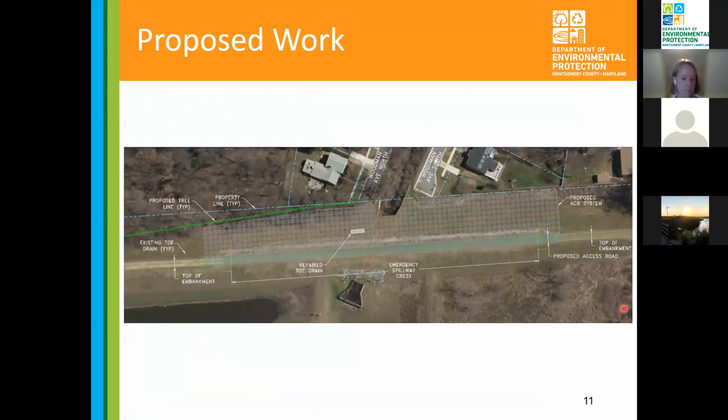This is good. So if you look at the riser in the bottom, and then you see that kind of U shape right above it. So the box culverts, which will act as a principal spillway, the water will go into the riser, through the principal spillway, and then out into the channel. And so the head wall is actually just that U-shaped, or I guess J-shaped, that he's pointing at, and that's just a concrete wall that provides some clearance. And it holds the dirt back so that way the water can flow freely.